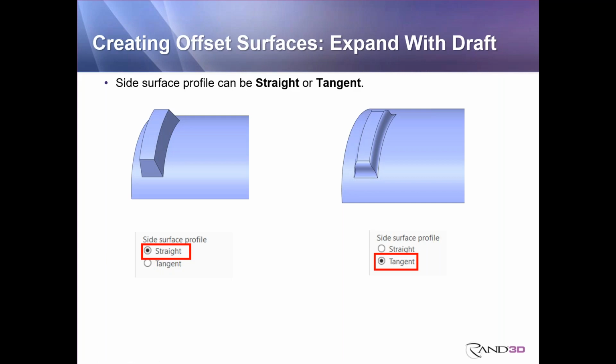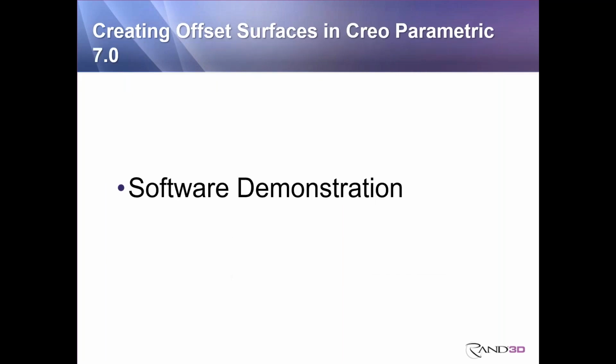So that's the offset feature. There's the standard offset that can be approximated if it doesn't fit with the automatic fit and the control fit. Then there's the expand that either offsets or translates the surface and fills in with continuous volume between them. And then if you want that expand to have draft, there's the third one called an expand with draft. So all looks like that.